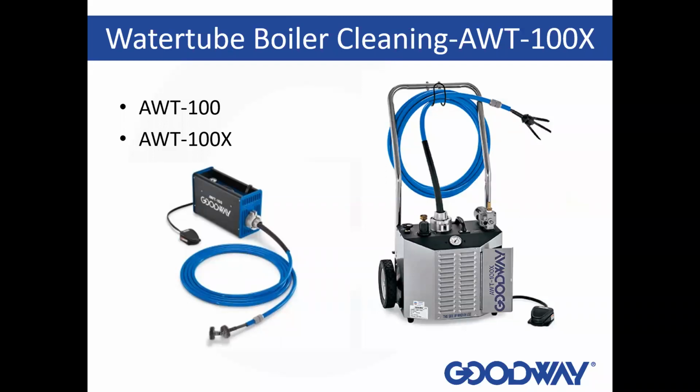So as he's going down the tube, if it was a water tube boiler, you would have water being injected out through the jacket of the flexible shaft. So it's kind of giving the scale that you're scraping off somewhere to go as you're cleaning it. Or if you were cleaning a fire tube boiler where you do not want to add water to the cleaning mixture, you would just use it dry, and you would go down the tubes and have the soot vacuum pulling the soot out for you at the same time.